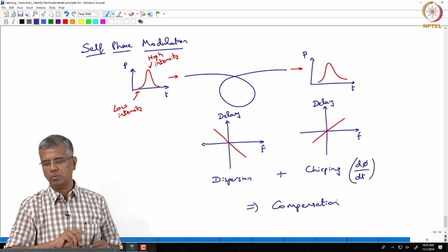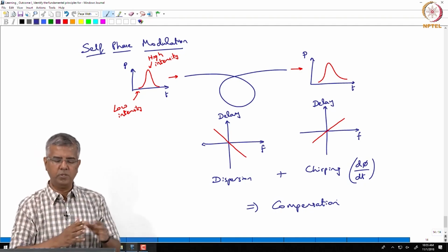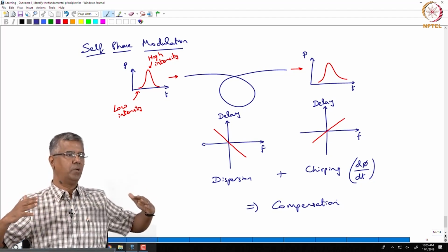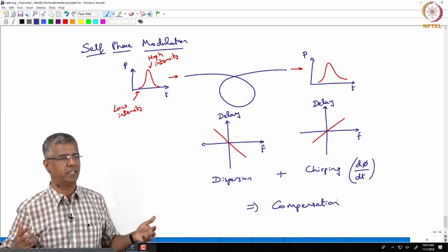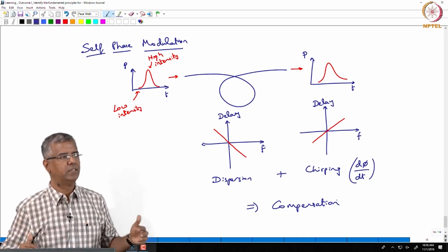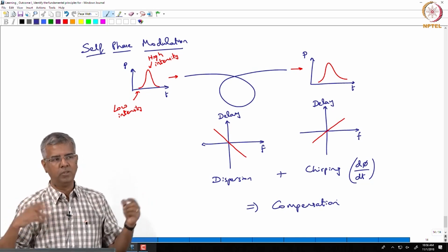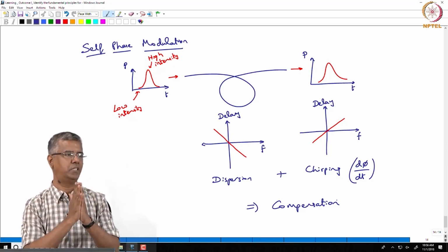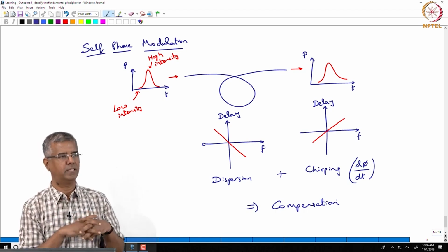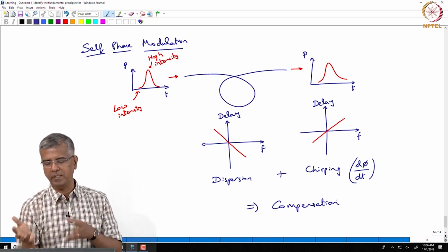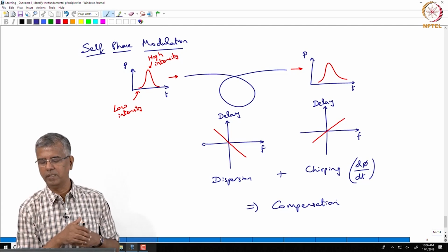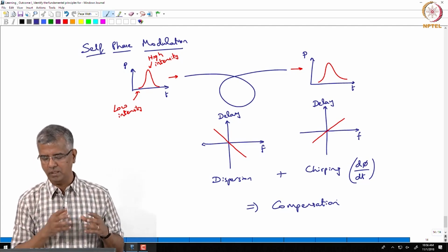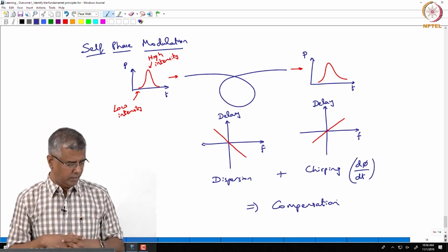Okay. So normally with your dispersion you would say, okay, your pulse is going to get wider and wider, but in the presence of self phase modulation you can actually offset dispersion and you can actually keep your pulse shape intact, right? You understand that? So chirping in this case can actually be a good thing, that it can be used to offset dispersion in fibers. So we're out of time.